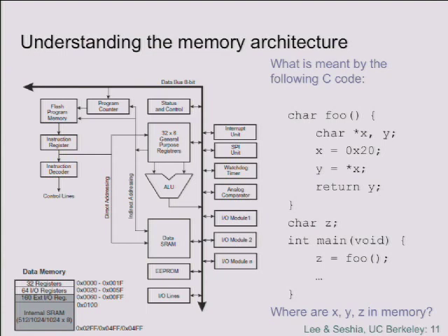Z is in the globals, right? And it's kind of up to the compiler what to do, but a pretty typical thing for a compiler to do is to put the globals at one end of the internal memory. So it'll start at this address, okay? Allocate memory for your globals, your static variables, is what they're called in C.